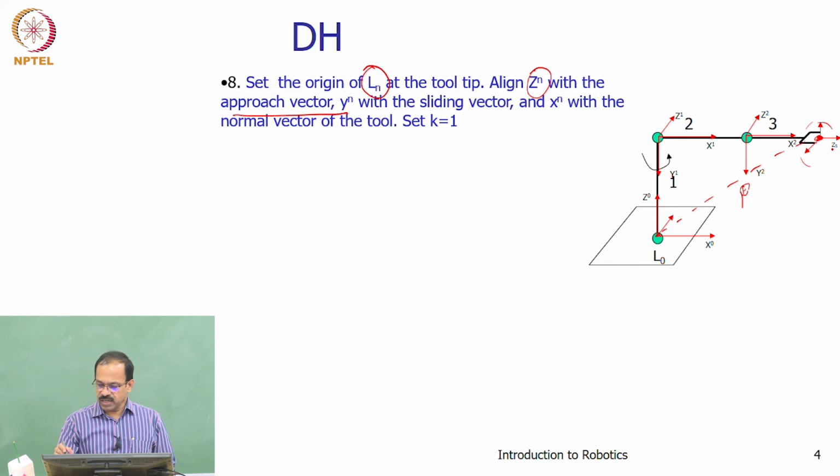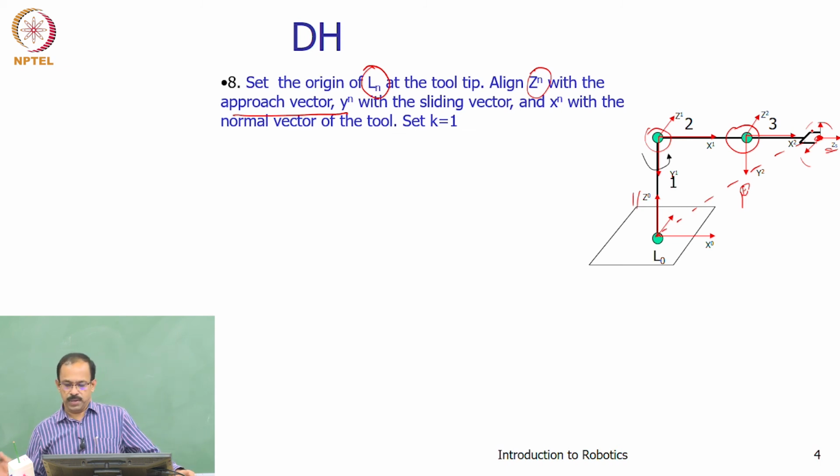You can see the z-axis is like this, but here it is like this. So there is a rotation of this coordinate frame with respect to the base frame, and that depends on all these joint motions. All these joint parameters will affect the position and orientation. We need a concise formulation which will take care of all these elements.